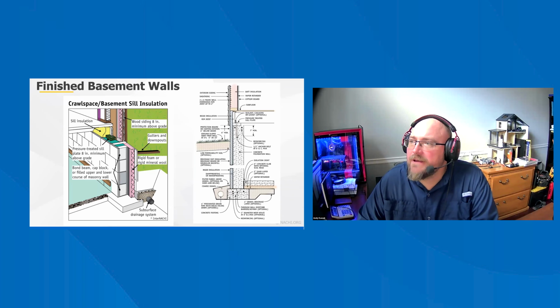Finished basement walls. Finished basement walls are exposed to many different things that come from all directions. The finished basement wall is exposed to different temperatures, moisture levels, water vapor movement, heat, cold, cool concrete, warm interior air, etc. And they all relate to the biggest concern with basement finished walls: moisture, specifically exterior moisture.